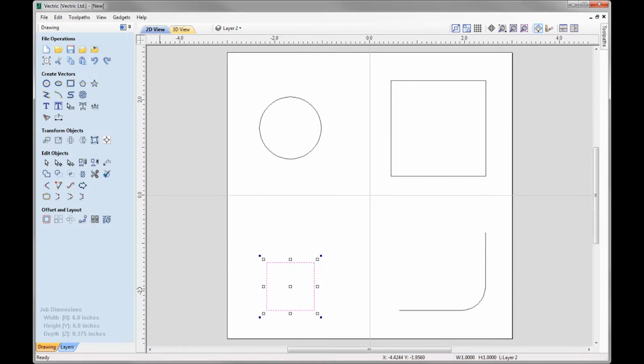So not only can we make use of the Smart Snapping when drawing shapes and aligning shapes, but we can also make use of it when we're in Node Edit mode. For example, with this square selected, let's press N on the keyboard. I'm going to press C to cut this point here, then take that node, and you'll see that I'm able to follow along that vertical extension there.